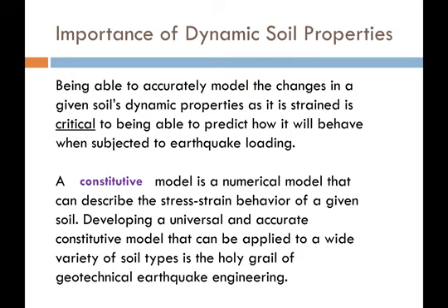of pore pressure effects. As you start to strain soil back and forth, the pore pressure inside the soil does wacky things. And if the pore pressure does wacky things, then the confinement or the effective stress in the soil does wacky things too. And so you can get the soil beginning to gain stiffness as you strain it, and that's called dilation. And then it can suddenly lose stiffness as pore pressure goes up again.